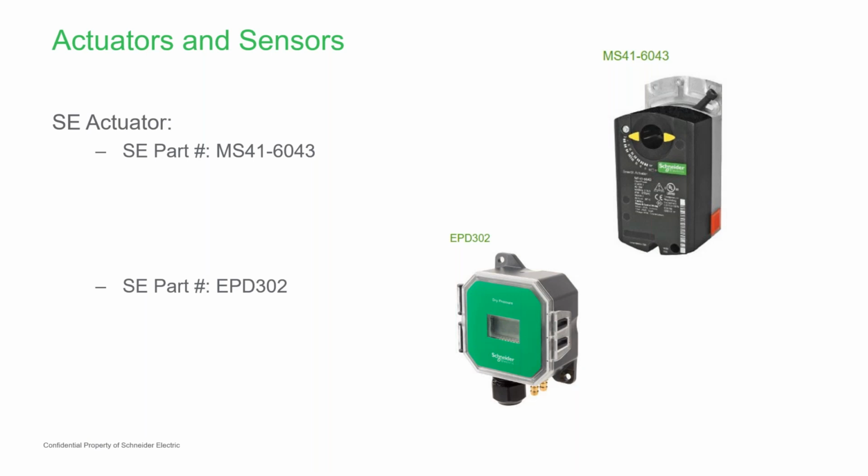And then on the pressure transducer, it must be a 0 to 10 volt unless you write a Lua script. There's no choice other than 0 to 10 unless Lua is written. You can do a 0 to 5 if you wanted to. And the reason for that is we give you the programming capability in the room controller on the HMI to scale it, right? So it's always 0 to 10, and it allows you to do any range of 0 to